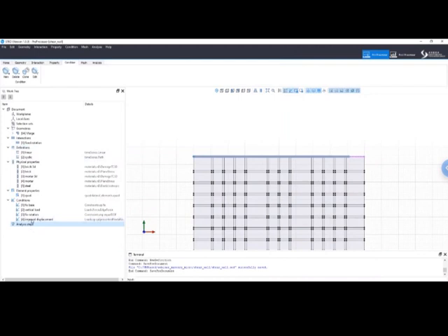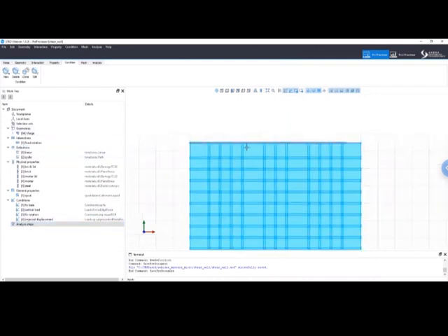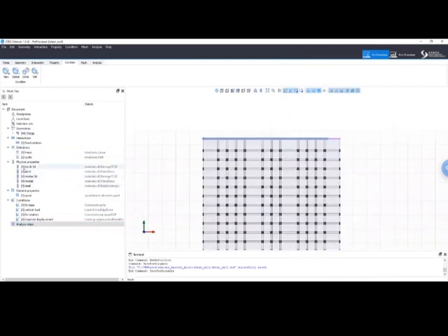This is very important because up to here, what we have done is to create our model, to assign the constitutive models and the finite element formulation, and then we created and assigned the boundary condition. As you can see, they have just been defined. The boundary condition, they should be defined, but then you need to specify when to apply them in the analysis steps. So here, everything we will define in the analysis steps. Their order will be extremely important because the order in which you put analysis step is the same order in which that command will appear in the OpenSees script file.